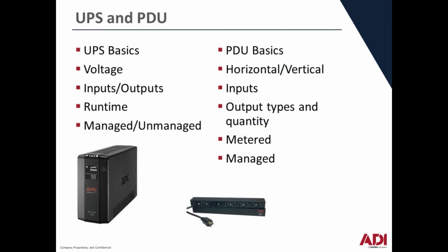This slide shows some of the key components in choosing the right PDU or UPS for your project. In choosing the right UPS, you'll need to know the voltage requirements, quantity of inputs and outputs, runtime needed, and whether it's managed or unmanaged. When deciding on what PDU to use, you'll need to know: is it vertical or horizontally installed, the inputs, output types and quantity, and whether the PDU needs to be metered or managed.